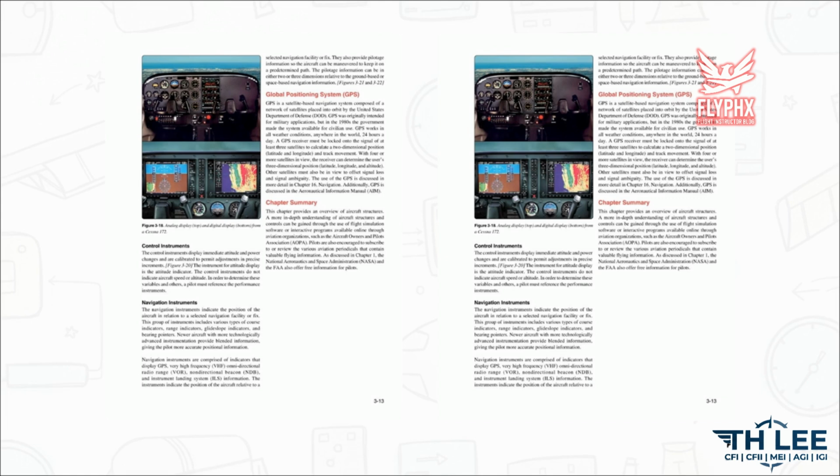The screen directly in front of the pilot is called the primary flight display, or PFD. The second screen, usually right in the center of the panel, is the multi-function display, or MFD. These solid-state instruments brilliantly declutter the instrument panel while massively increasing safety, boasting a failure rate far, far less than those of conventional analog gauges.